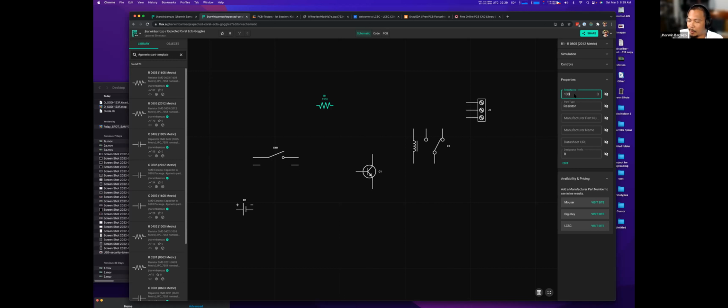So just drag the package size that I want. If you look in here, there are 2 resistors and 1 LED. So I just need to copy this one and paste it in here. And I just need to change this resistance to 1K because the other one is 1K. And for the LED, I'm going to stick again with the same size, 0805.